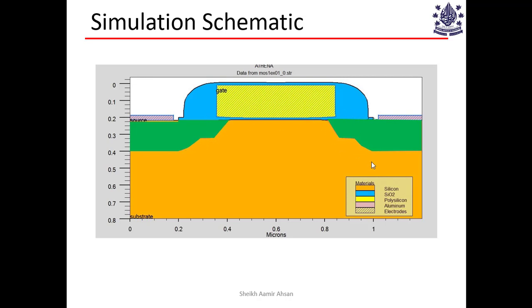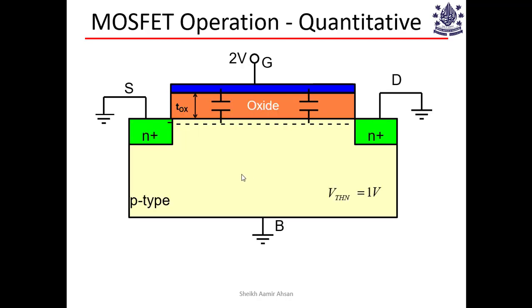This is called the drain-gate underlap. And this does lead to some kind of parasitic behavior. This is just an anecdote that I'm mentioning. Additionally, you see these spacer layers on top of the gate. These are also typically used in advanced MOSFETs. But I'm not going to go into too many details here because this is not a device course.